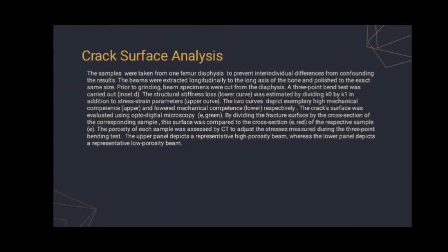The cracked surface was evaluated using an opto-digital microscope by dividing the fracture surface by the cross-section of the corresponding sample. This surface was compared to the cross-section of the respective sample. The porosity of each sample was assessed by CT to adjust the stress measured during the 3-point bending test. The upper panel depicts a representative high porosity beam, whereas the lower panel depicts a representative lower porosity beam.